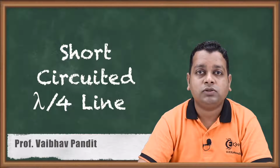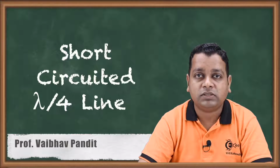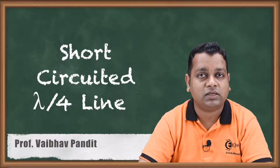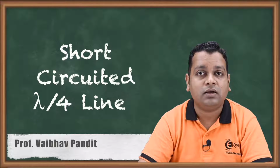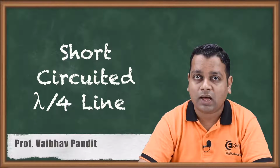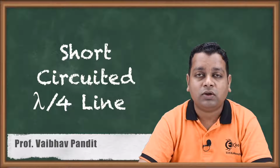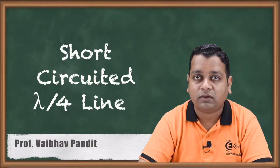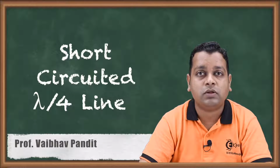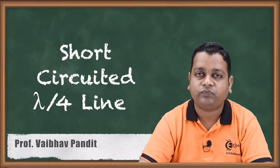Next to that, we also added information regarding quality factor measurement when these RLC circuits for series and parallel connections are connected to the load resistance RL. So now we have the knowledge of the unloaded quality factor, the external quality factor, and the loaded quality factor also.